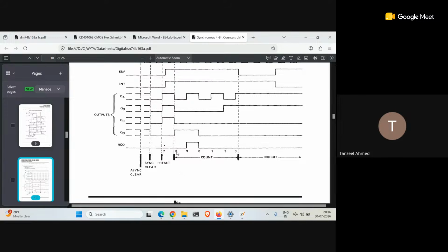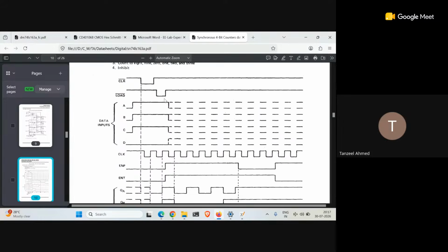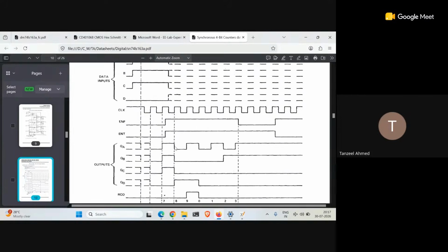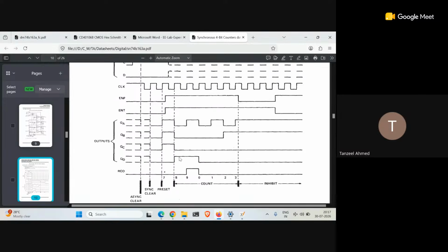On the next clock cycle, 7 has become incremented to 8. In the middle of 7 and 8, they made sure to send enable signals to high, which will start the counting, and the other control signal they managed to send high as well. So they set load to low, it got sampled at the rising clock edge, and that allowed whatever was put into the input bits to get loaded into the output on the next clock edge, right? And then they set load up before the following clock edge arrived. In the middle they also sent the enable signals high, and that is how at the next clock edge the 7 turned into 8. Here you can see the MSB going to 1 and the 3 lower bits are 0, and the count has started.